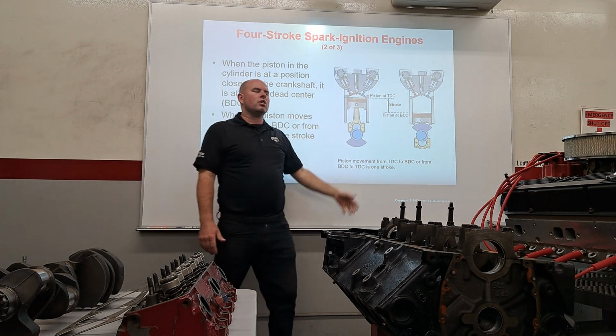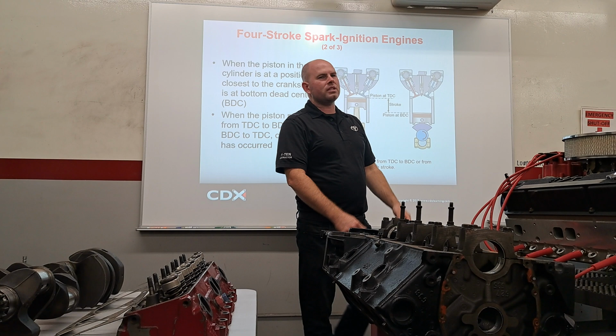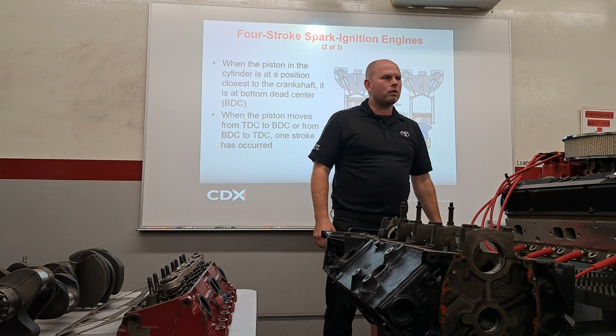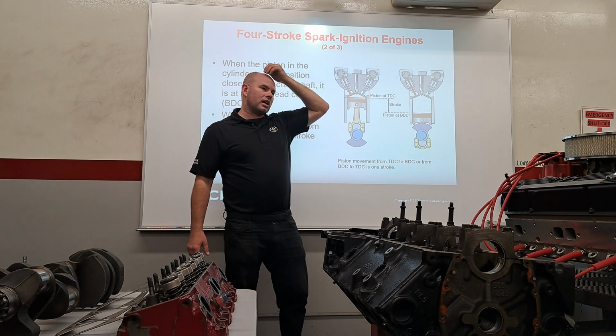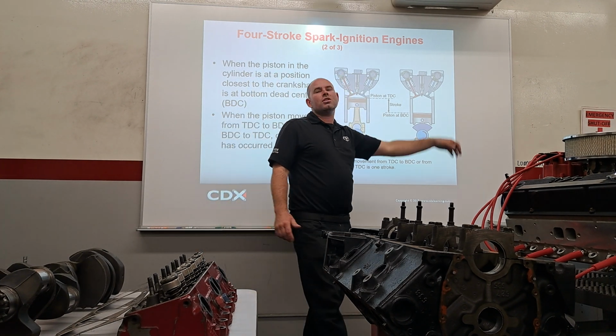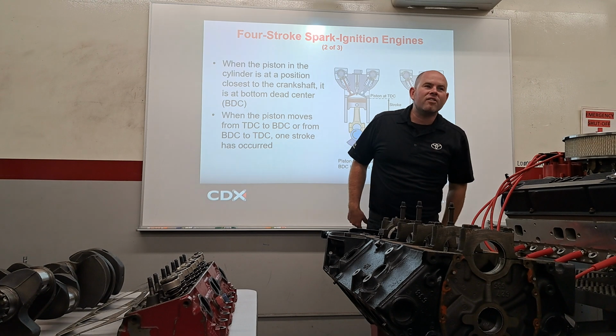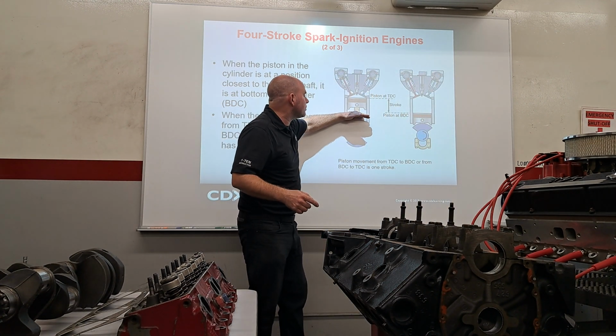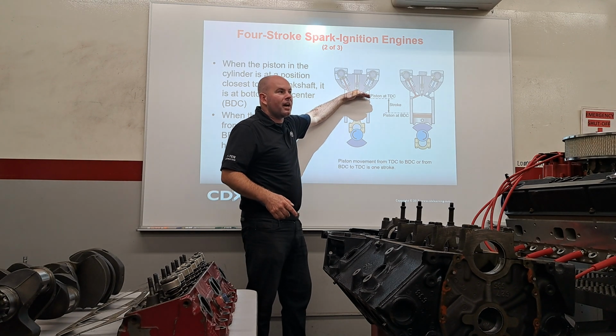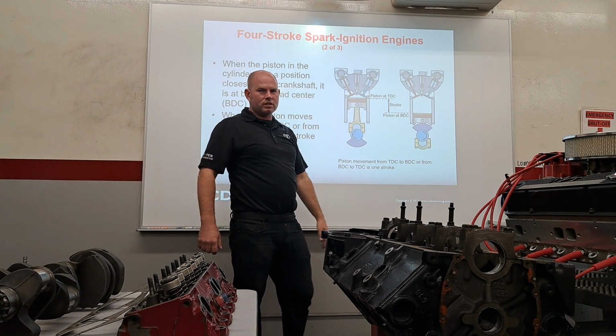So if you're working on a vehicle and it says set cylinder number 1 to TDC, you're like, what? Well, I just told you. How are you going to figure out cylinder number 1 is at top dead center? Well, how janky do you want to be? You get your screwdriver out, you take the spark plug out, you drop it down there, you turn the engine over, and the screwdriver goes up, and then it goes down, and then you're like, back up a little bit, there you go, there's TDC.